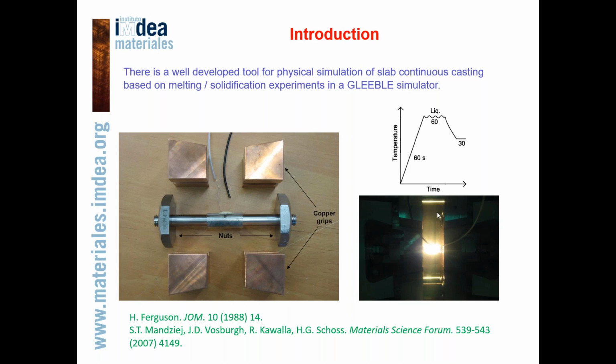So in all our tests, the material was fully molten and solidified in the midsection. As you mentioned, the experimental test did match the real casting, so there is high confidence that it is fully melted. Also, the photo on the right side shows the melting solidification experiment on MAR M247 using a quartz tube.